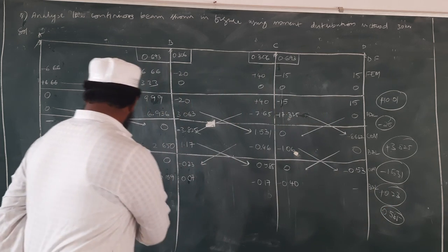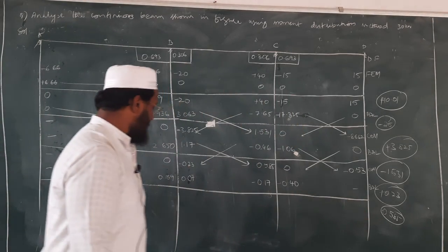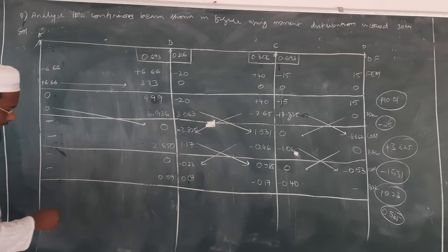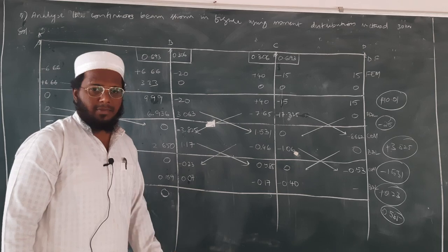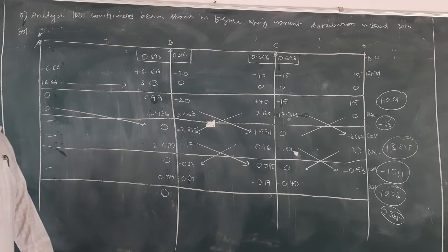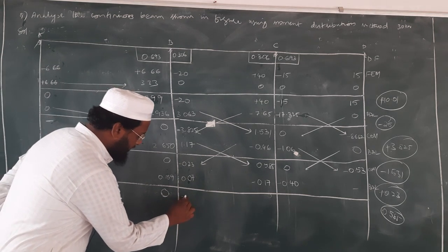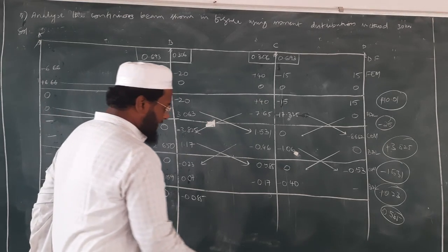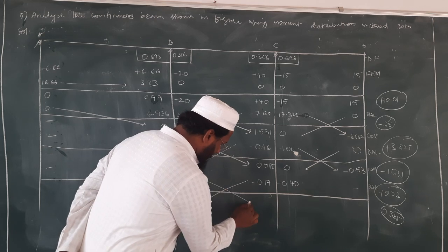Okay. Now after completion of this balancing, draw the line and carry over moment. So I cannot send this value here. So it is 0 here. So minus 0.17 divided by 2 is how much? Minus 0.085. Next here I have taken this value, I will send this value here.